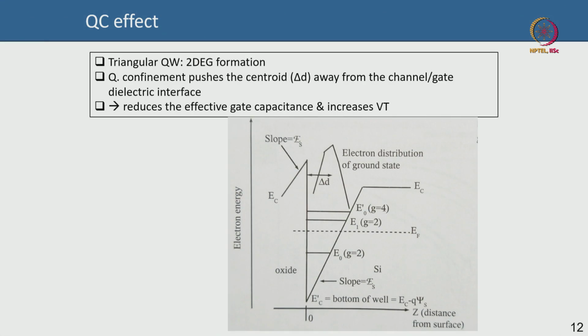So, we shall continue our discussion on nanoscale MOSFET, general purpose nanoscale MOSFET. Last class we discussed drain induced barrier lowering, and we also talked about the threshold voltage roll off in highly scaled devices. So, today we will continue the discussion and move to other topics here. The next thing to understand is the charge quantization effect, or quantum capacitance effect.